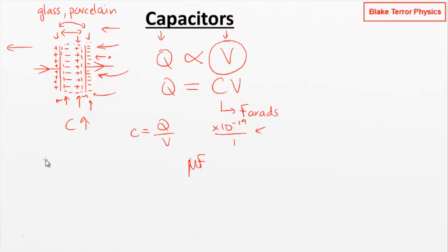So if you hit a breakdown voltage, there's a couple of things you can do. You can separate the plates more. You can make the capacitor bigger all round. If you separate those plates by more, then you've got a lower potential gradient between the two plates. You might still have the same potential difference, but it's acting over a larger range in space.